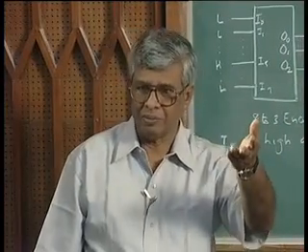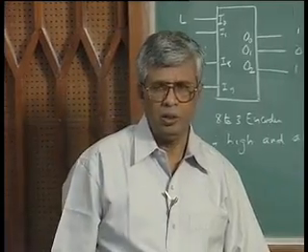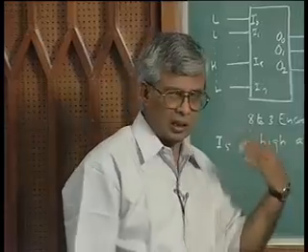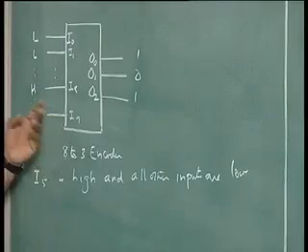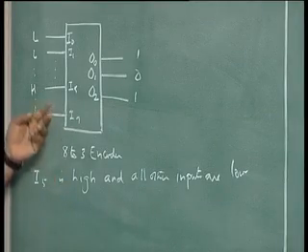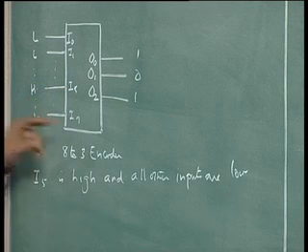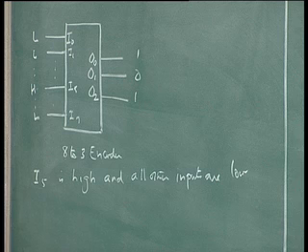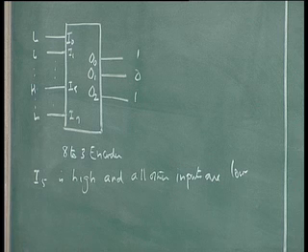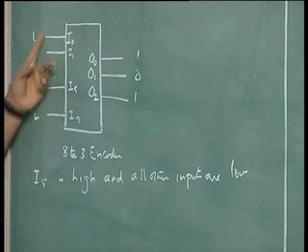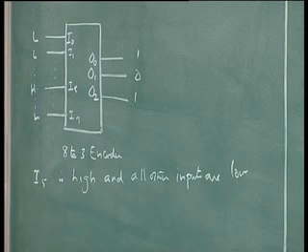It is one scheme, that is all. The rule is you make the rule and then build a circuit accordingly. Or I can say higher inputs have priority, that means if along with I5, I6 also is active high, I can say I6 should be recognized and not I5, fine, then the output will not be 101, it will be 110. So, anyway, this is called the encoding process of reducing the number of bits into a smaller number of bits without any loss of data.